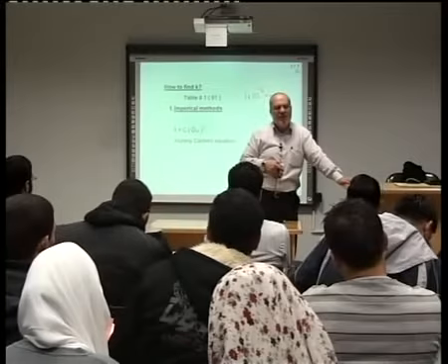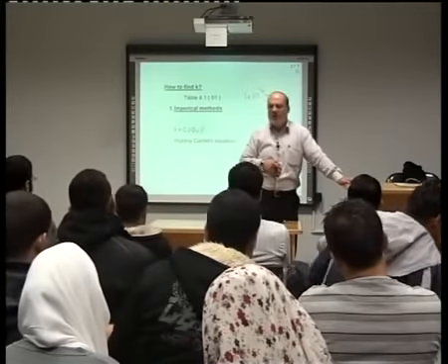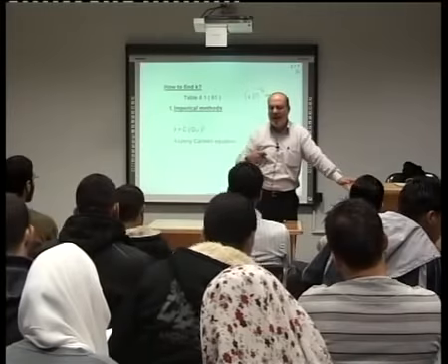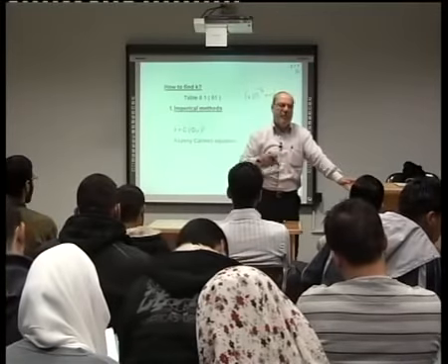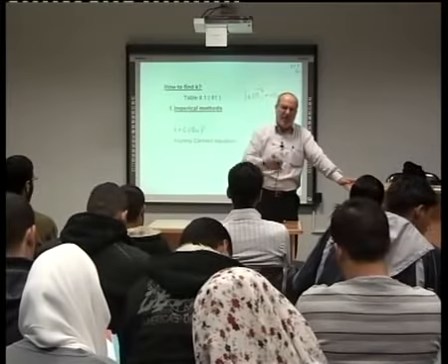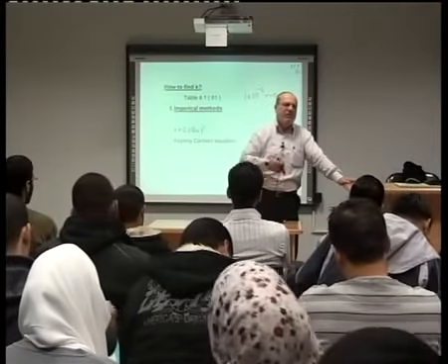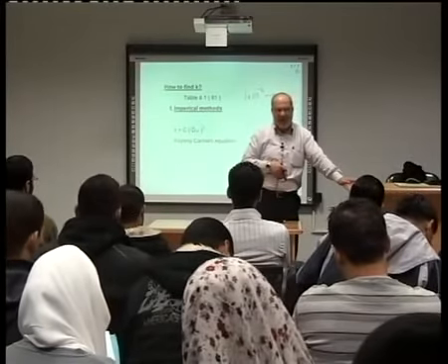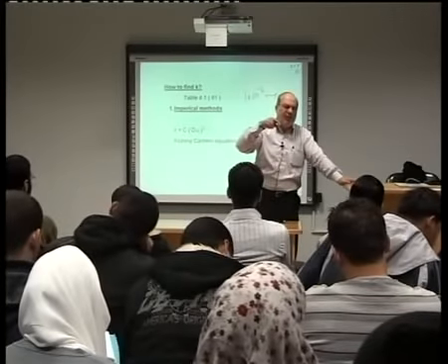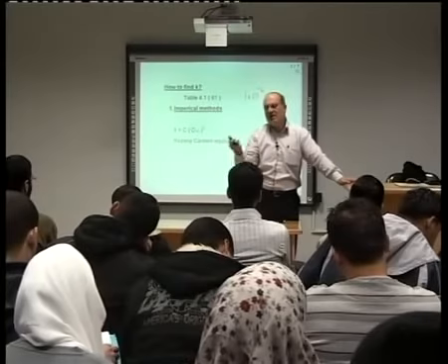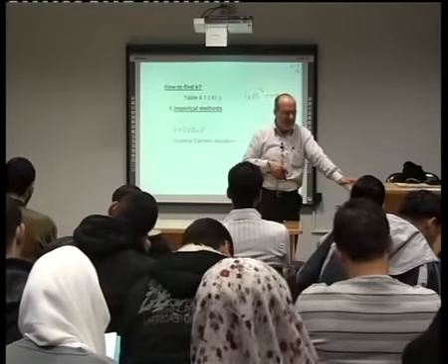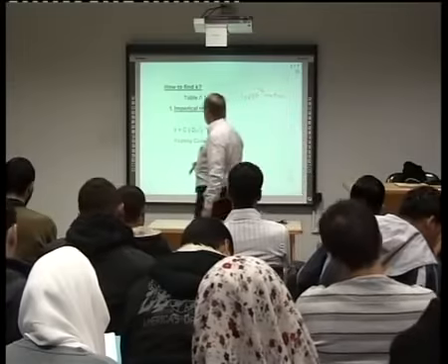Permeability in sand and gravel: as greater the particle size, K will be high, or K will increase. As smaller the particle size, as smaller the coefficient of permeability K. Okay? That's why we have problems with water in clay more than in sand. In sand we don't have it. In clay we have it. Okay? Now, let us see how to find K.